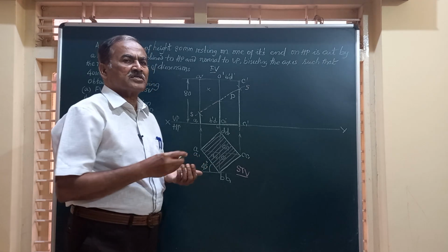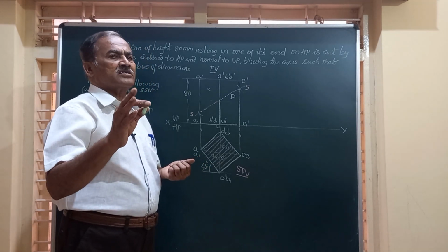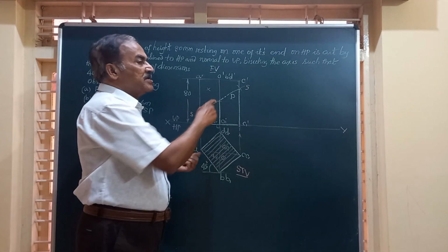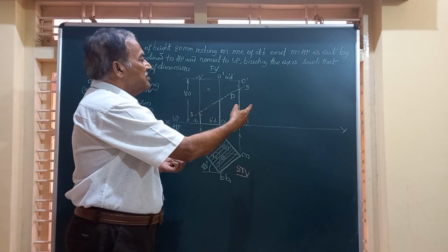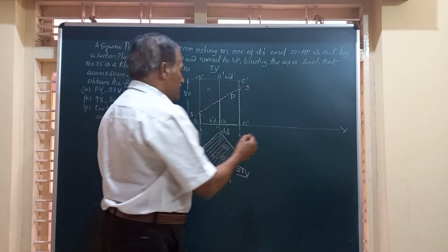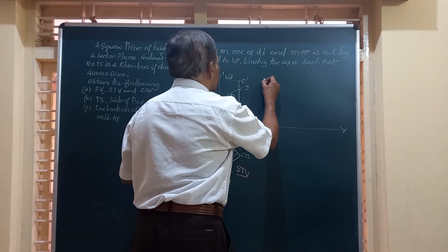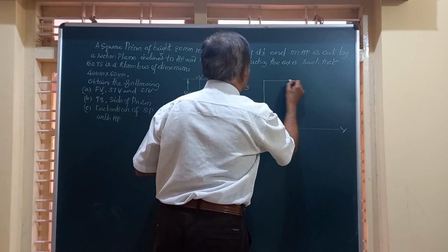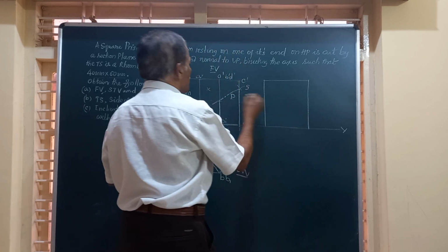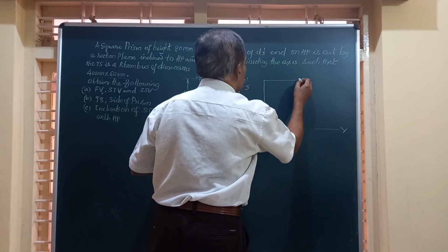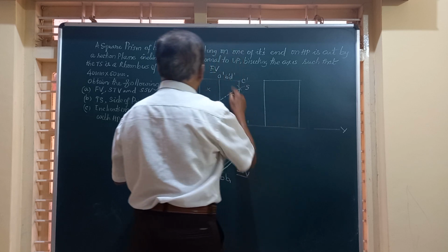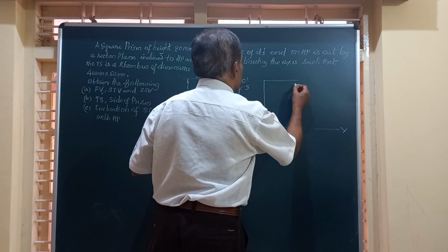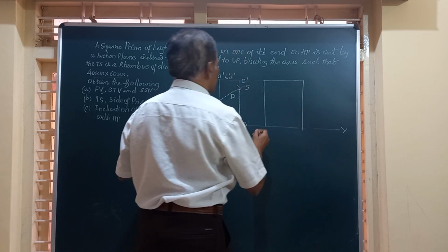How to obtain the sectional side view, friend? For cylinders, square pyramids, and square prisms, whatever front view you have got, the side view will be just a photocopy of that. So friends, I am going to construct here the left hand view or left side view of the figure, having height equal to 80 and this width will be the same as this. So let us say this is how it appears.